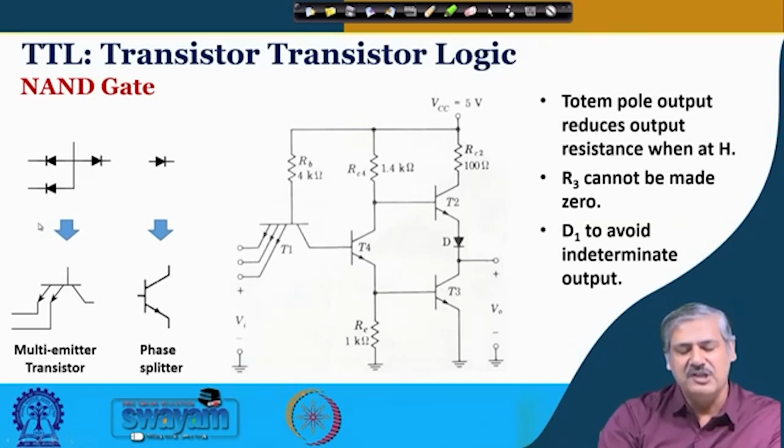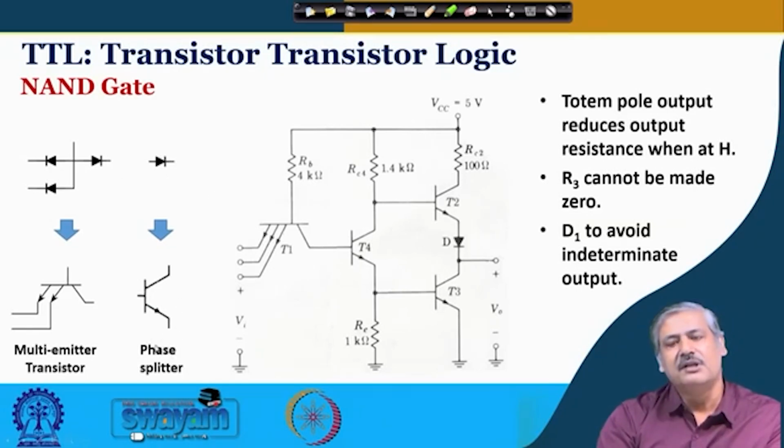This is the block which is coming in place of the one that we had seen in the DTL case. There was a diode over here, one level shifter, the second one that we had seen. So, this level shifter is present here as a transistor. This base emitter junction is providing the diode kind of drop that is required, clear.